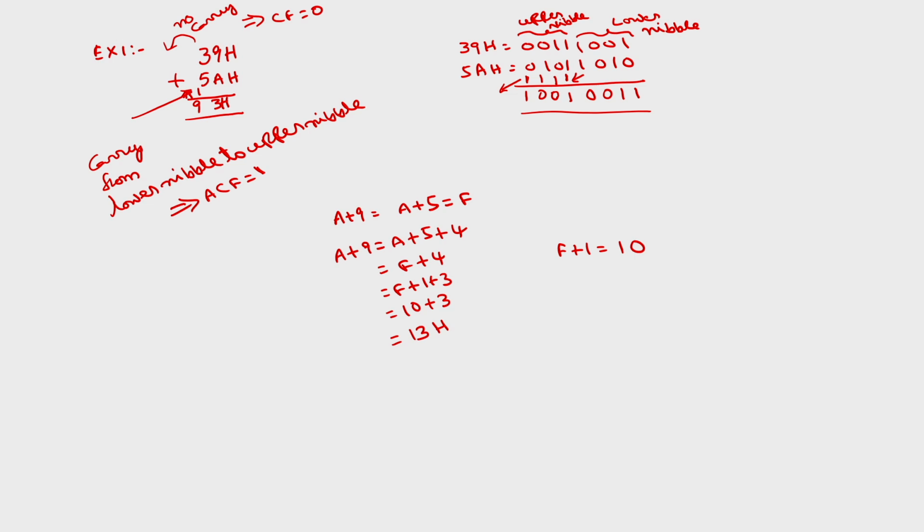There are two instructions, like decimal adjust accumulator, DAA. While discussing the instructions, we will see this auxiliary carry flag will be used in this instruction. Similarly, we have decimal adjust after subtraction. There are two instructions, and the auxiliary carry flag will be used by these two instructions.